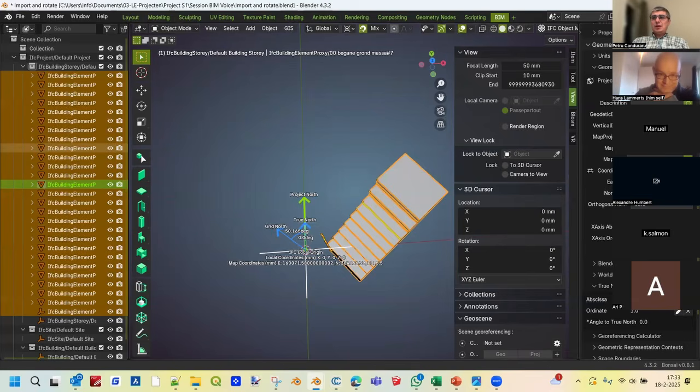Somebody said that they tried to edit the width of a wall in VS Code and then see it in BIM Viewer, but nothing happened. Well, if you save it, you have to save this as IFC. It will export to IFC and save in the IFC file. If I make this like 0.2, and here we can adjust the angle by 20, but these are just values. This is metadata. It does nothing with the model. It's just metadata of the origin of your model. Nothing more, nothing less.